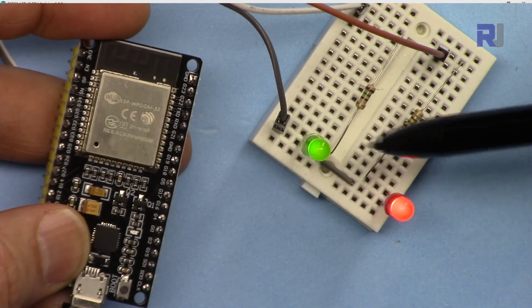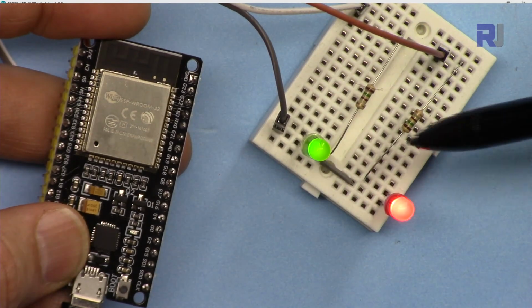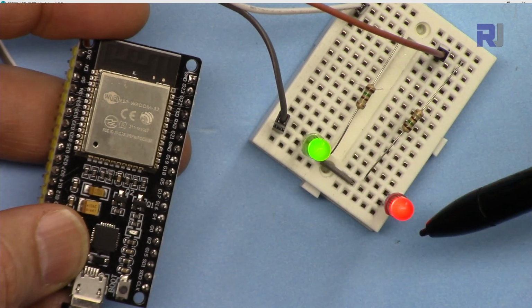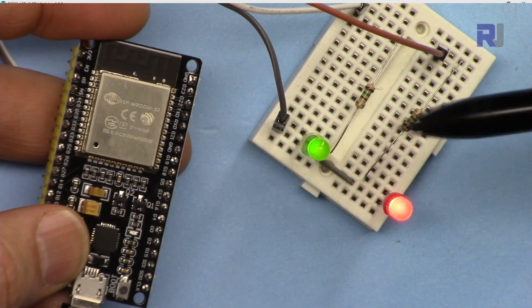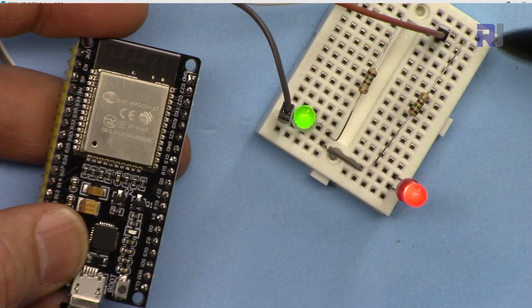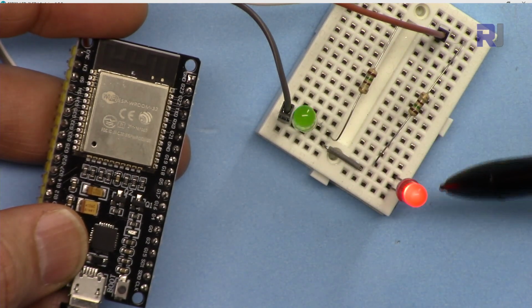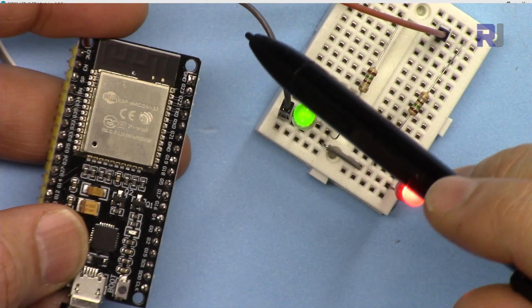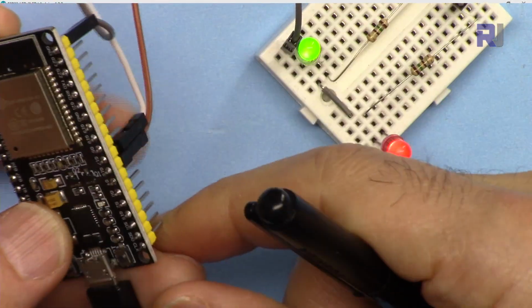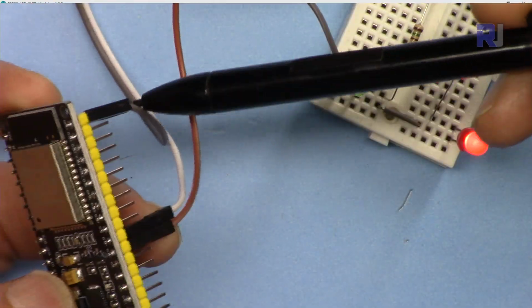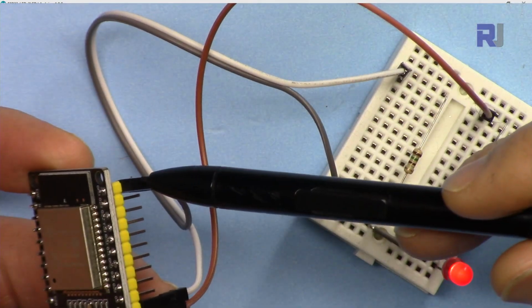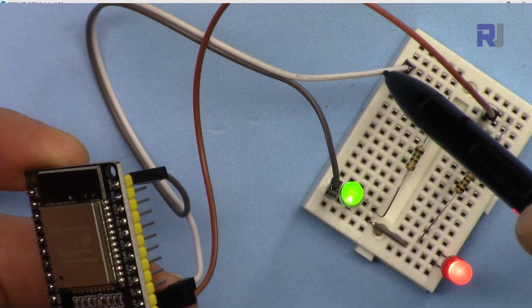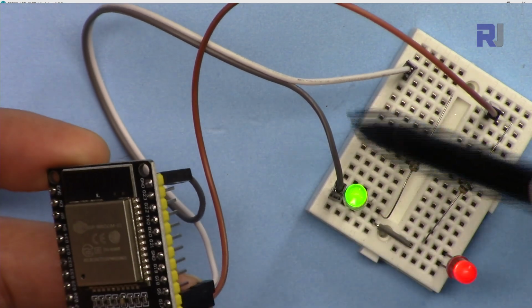And here is an example of fading two LEDs. One is fading at a step of 5, the other one is changing at a step of 10. So this one is fading faster and that one is slower, with ESP32. I've added another resistor and LED, and the ground is connected through this wire. For the wiring, the ground from this point is connected to the ground. This red is connected to pin 16 and the white is connected to pin 17. So these two are used for that purpose.